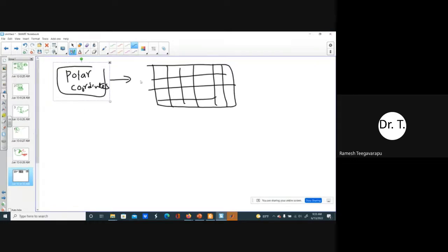But of course, I didn't elaborate more on the mean field bias corrections, which is not very difficult. If you have observed and radar-estimated values available for different time intervals, you compute the gauge over radar ratio. This will be sometimes more than 1 or less than 1.